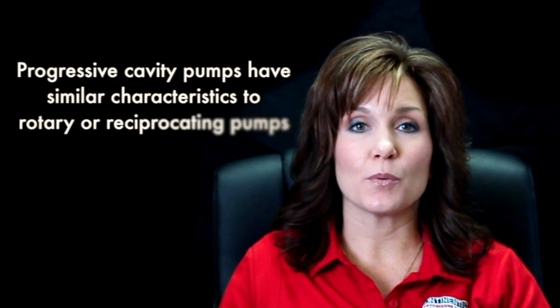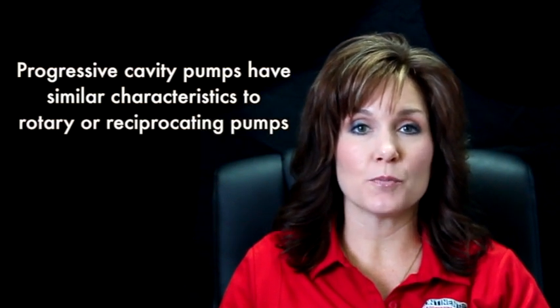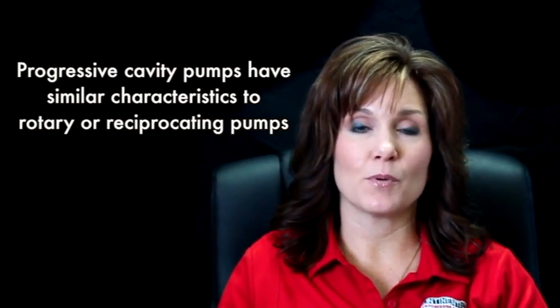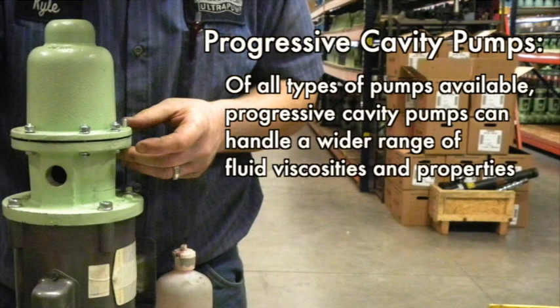Progressive cavity pumps have similar characteristics to rotary or reciprocating pumps such as piston, diaphragm, lobe, and screw pumps, with the one common feature of sealed cavities and operational similarities, like being able to pump at extremely low rates to even high pressures. The similarity between other pumps and progressive cavity pumps generally ends there. Of all types of pumps available, progressive cavity pumps are able to handle a wider range of fluid viscosities and properties than any other type of pump.